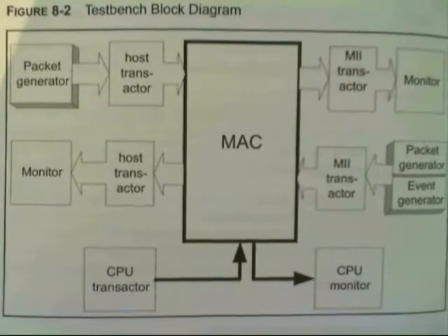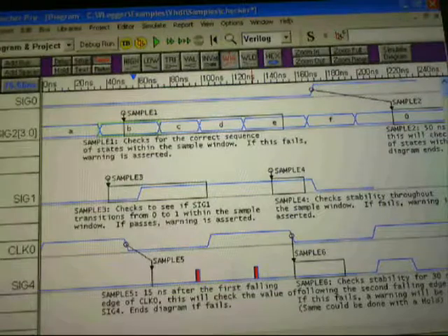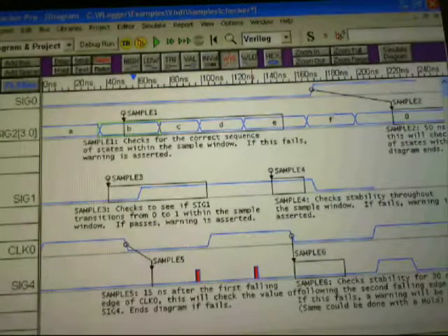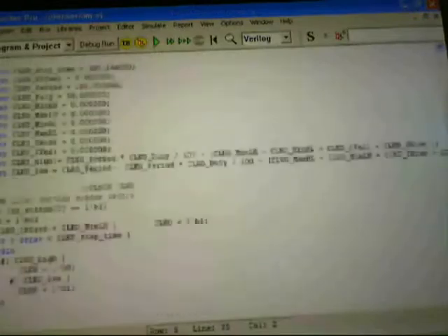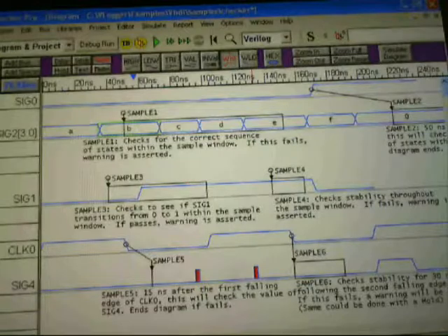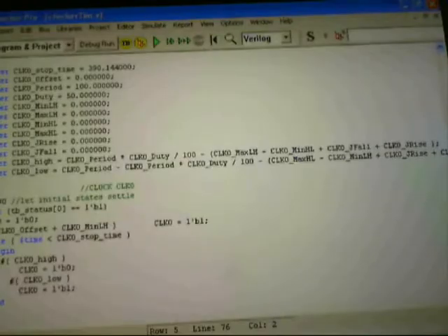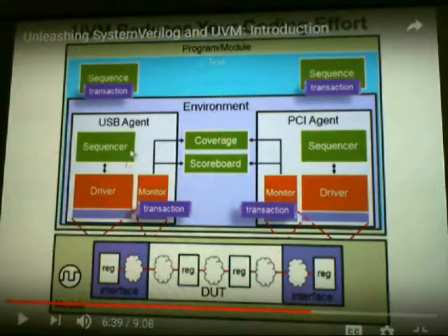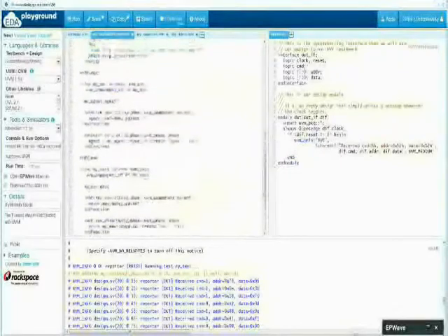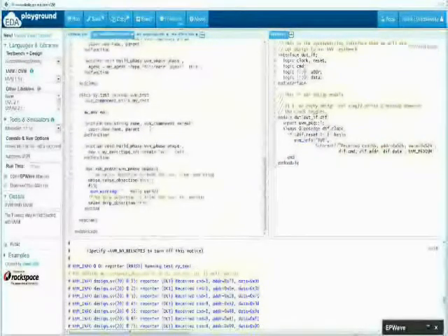The network events include collision. The MAC test bench sends packets in full duplex mode, produces random number generator functions, provides polymorphism, supports cycle accurate reference models, and also semaphore registers. There are two main types of formal verification: model checking and equivalency checking. In model checking, the verification engineer writes invariants for the DUT, design under test.